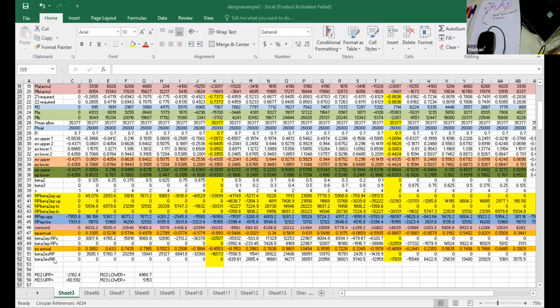If you want to shorten the length even for a longer bridge, you can reduce the number of sections. But here I have been very generous. Every 5 meters I have used a separate section so that I could easily generate the actual shape of the bending moment diagram.